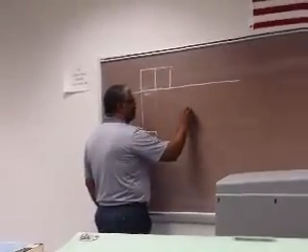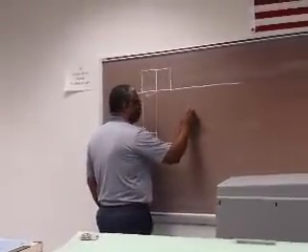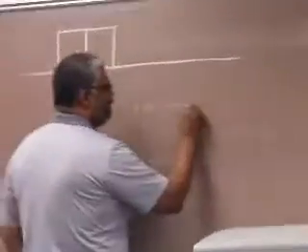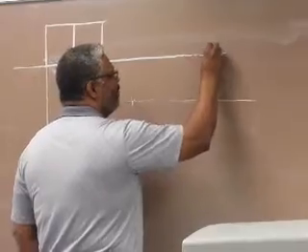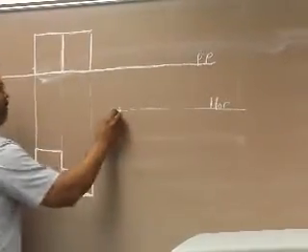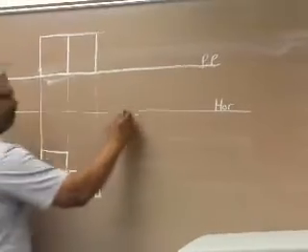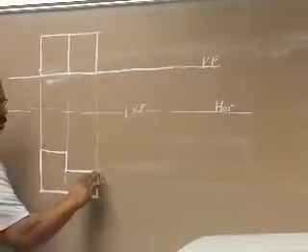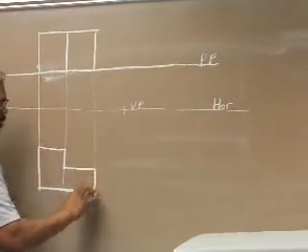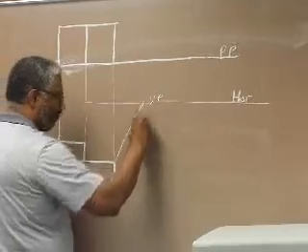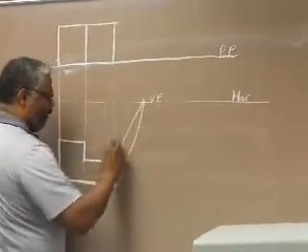So we arbitrarily, here we're just going to pick a vanishing point, and that vanishing point sits on the horizon. So this is my picture plane, this is my horizon, and that's my vanishing point. All my lines that show depth, where they intersect here in this view, go to the vanishing point.